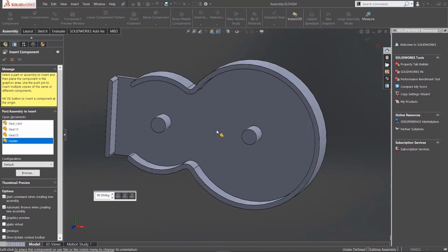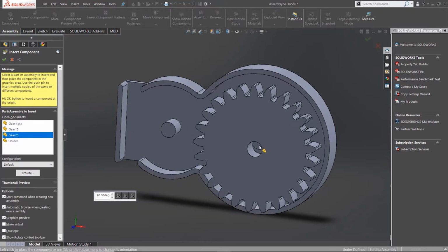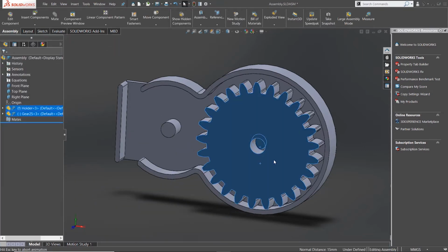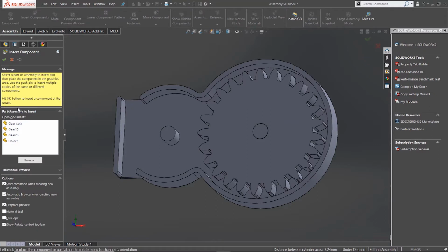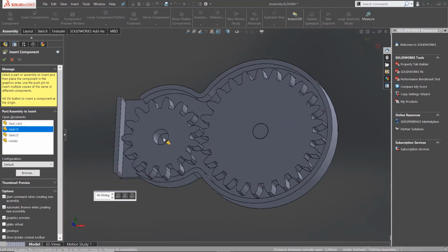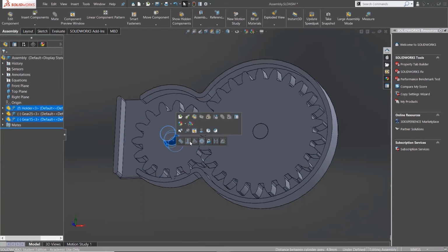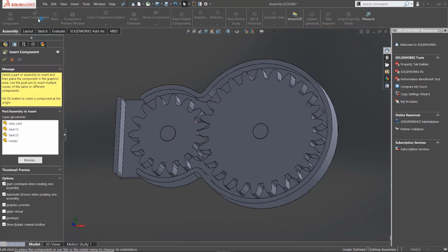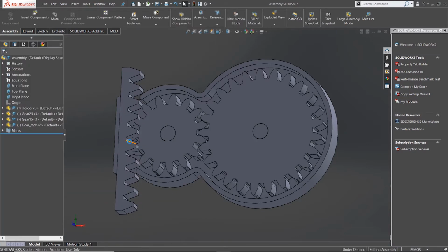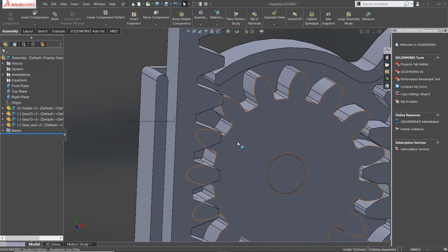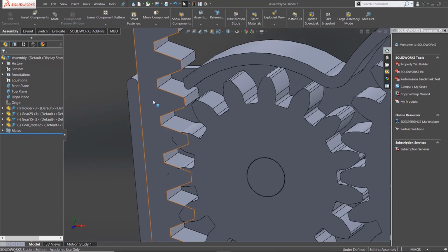Start with a holder. The center distance for the two gears is equal to the sum of the pitch diameters divided by 2. The gear rack position is measured on the pitch line. This needs to be tangent to the pitch circle of the gear. Place them into the right position, but keep it movable.